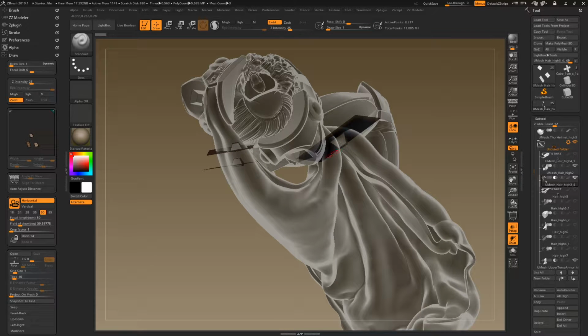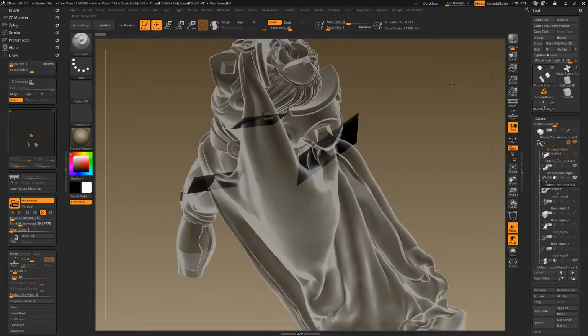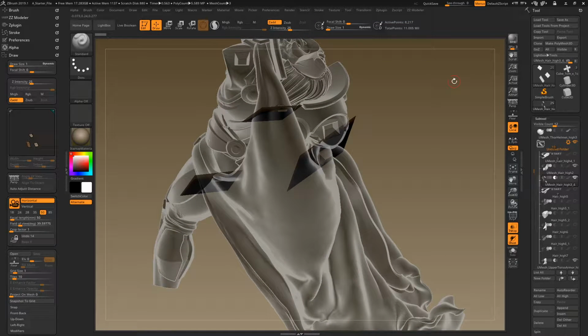down just a little bit, because all I'm looking for is alignment, and that's one of the things that, although a lot of people probably would argue with me about this, when I started learning keying, keys are not structural; they're for alignment primarily. When I say structural, I'm talking like adding a bolt or a pin or some sort of attachment ligament that adds structural strength.